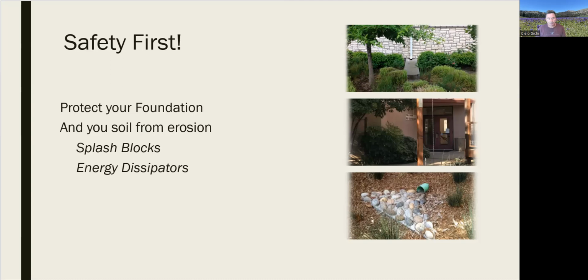Okay, so that's it for rain gardens. There's a lot to it. They are beautiful systems. You can incorporate amazing native plants, create habitat, and in the process, reduce the volume of water going into our waterways and the pollutant loading. Because when you're setting up these systems, the pollutants will settle into that planted area, and the life in that soil will actually break down those pollutants. The result is that clean water infiltrates into your subsoil, and any runoff that goes off is going off with less volume, and it's much cleaner.